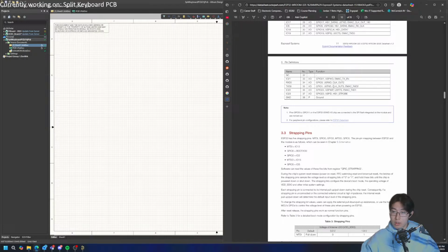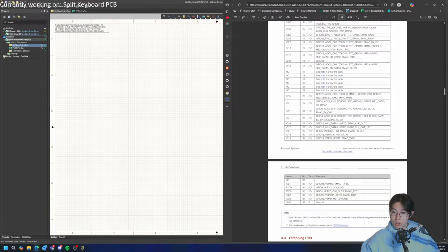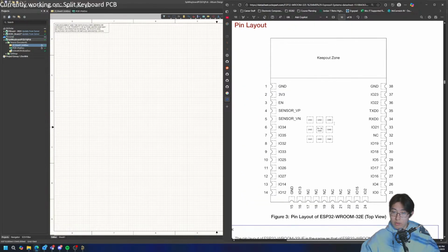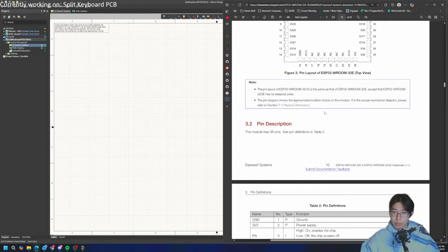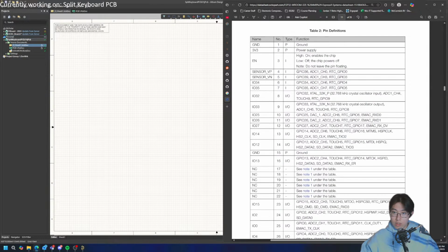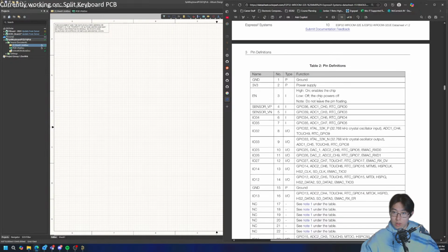Oh, okay. Gotcha. Okay, fair enough. What is sensor VP in VN though? GPIO 36. RTC GPIO 0. ADC 1 channel 0. ADC 1 channel 3.